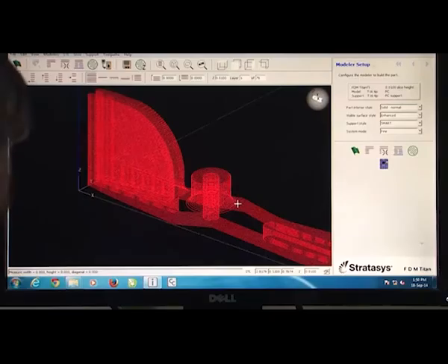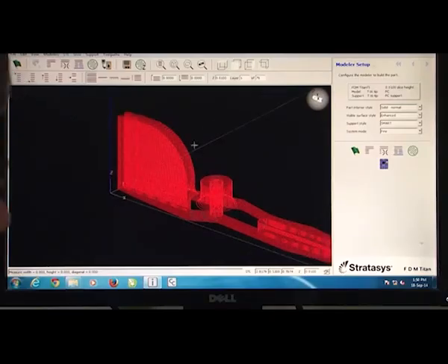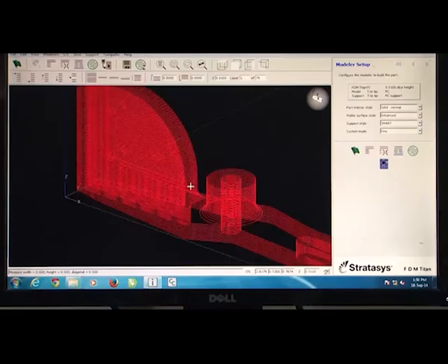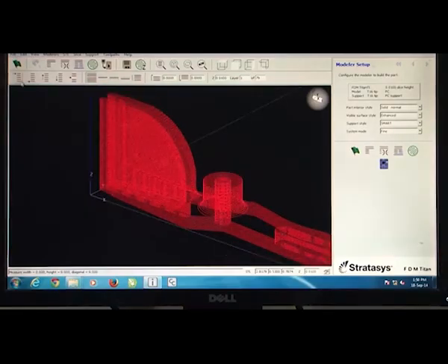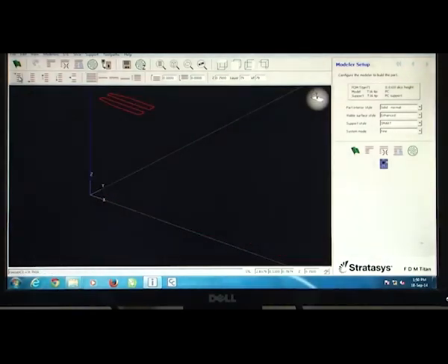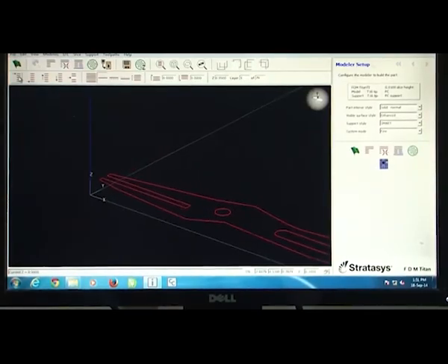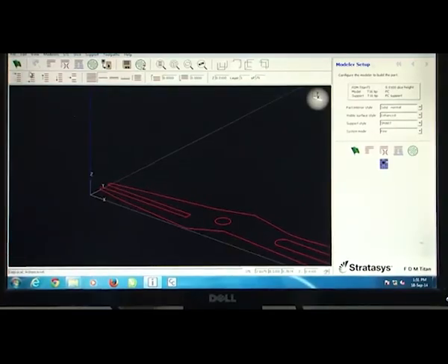Okay. And what I would also like to illustrate here is that once this slicing is made, you can also look at the independent slices by these options here on the left corner, where you can go from the top end, okay, and then with the page up, page down option, you can keep on varying this and see what are the various layers which you have to deposit. And in fact, this also mentions what is the tool path to deposit that layer. Okay, and finally you will see that the whole surface is being constructed based on that. Okay, and then you can also do it simultaneously from the top surface as well. And you can go up by doing the page up, okay, in a similar manner, and that is how typically you get all the support.